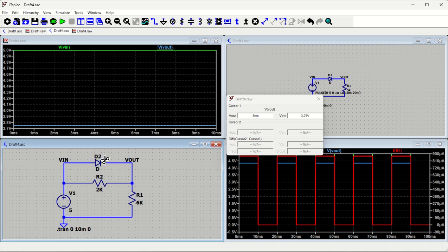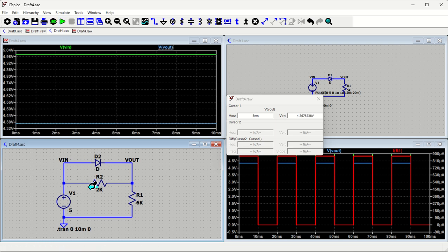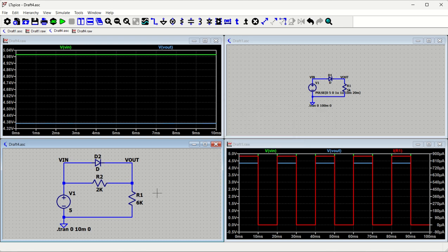Now once we put the diode, what is going to happen? Yes, so this is my diode that is put now. Now I'll run it. The voltage drop across this diode will be just 0.7, and this is how the circuit will not take the path of the resistor, it will take the path of the diode, right? So let's rerun it again.